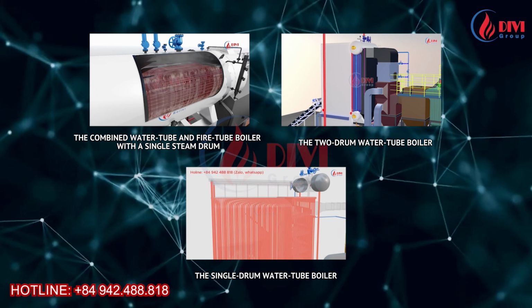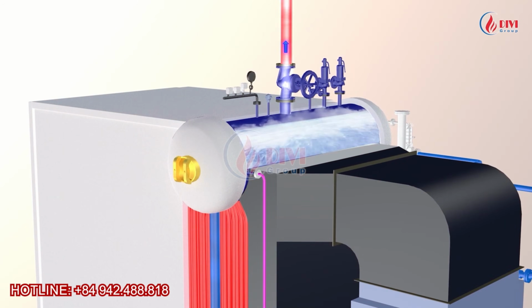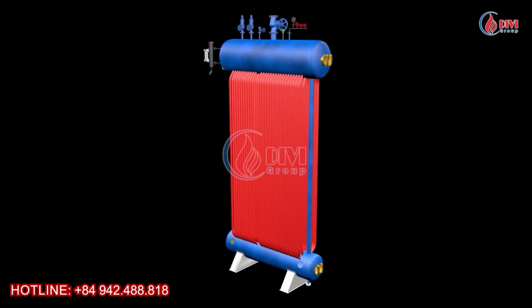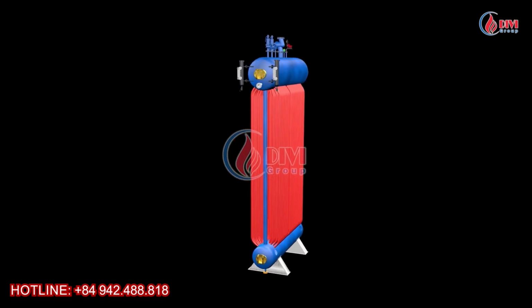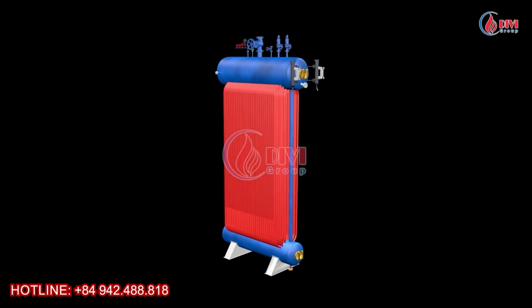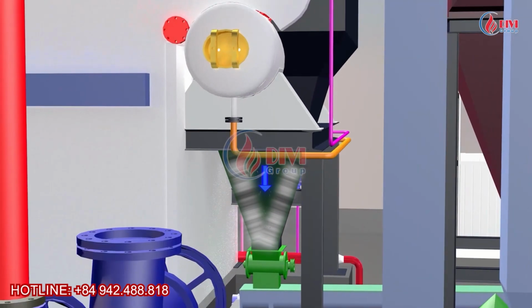Next, let's look at the two-drum water tube boiler. Compared with the combined water tube and fire tube design, a two-drum water tube boiler contains less water. Because it holds less water, it can produce steam much faster during startup. This is a significant advantage for plants that require fast startup or frequently experience changing steam loads. The lower drum also provides a place where sludge and some solid deposits can settle, helping reduce the amount of debris entering the generating tubes.